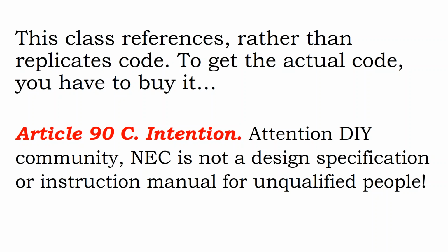Rapid shutdown is still there. The main concern about NEC 2017 was that they were going to require rapid shutdown not just at the array itself, which is a good idea, but to take rapid shutdown a step further and require every single module on the rooftop to turn off during a rapid shutdown situation, so that the power didn't just stop at the array where you still have higher voltage, but basically require microinverters or something like that as part of code. And the code did not do that. So the NEC 2017 expansions are all more clarifications rather than putting in new requirements, at least for rooftop residential and commercial solar design.